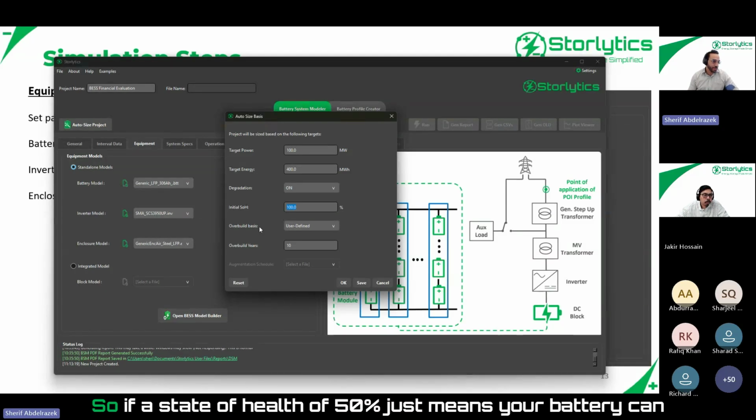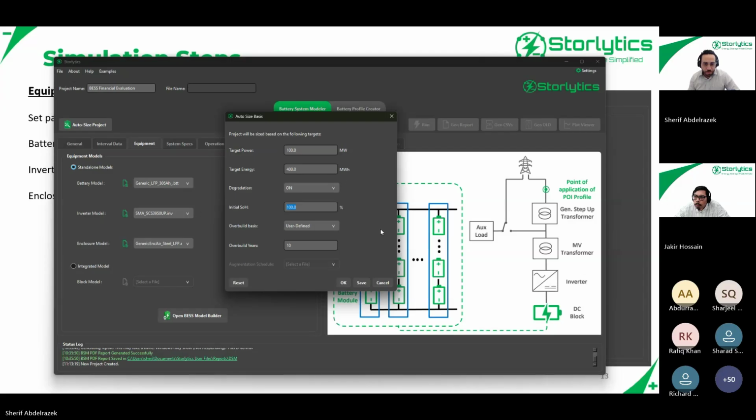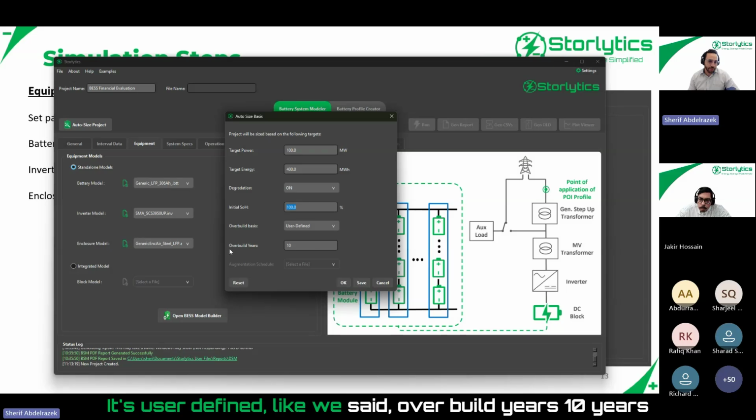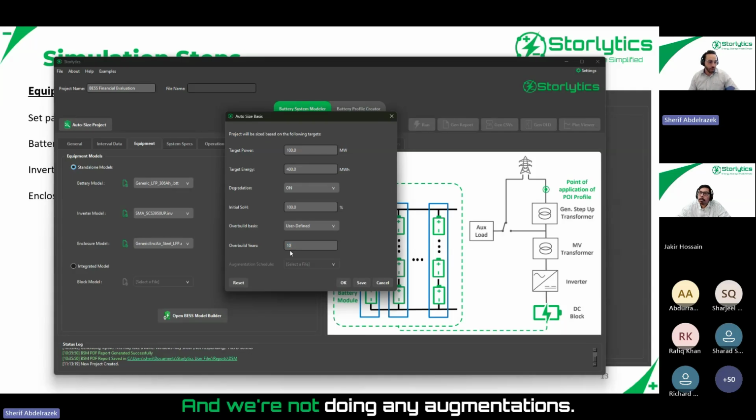So a state of health of 50% just means your battery can only hold 50% of the energy it could hold when it was new. Overbuild basis here is user defined, like we said. Overbuild years, 10 years, because the project life we're assuming here is 10 years, and we're not doing any augmentations.